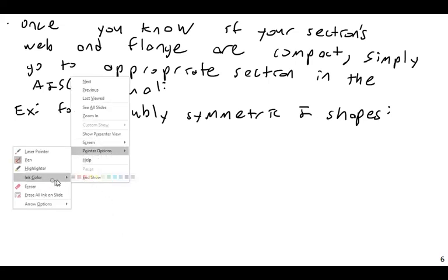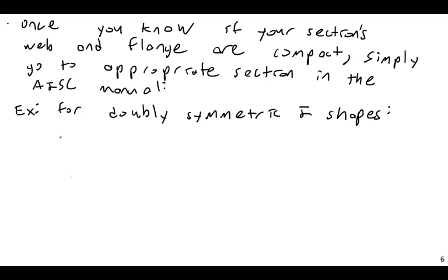we'll use F2. We're going to talk primarily in this class about section F2, really because that's the simplest one, and this is kind of a survey course of steel and concrete design. F2 is what you'll be using if you have both a compact flange and a compact web.